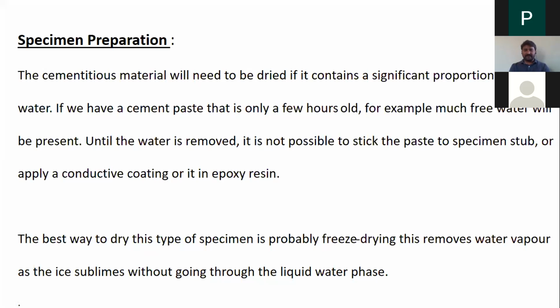Then we may use even diamond polishers to get a very fine surface, so that if the surface is very fine, the quality of images that we get will be very high. If the resolution is very high, then analysis can be very prompt. So sample preparation is very, very important. There are lots of papers available on sample preparation. Sample preparation itself can be a 1 hour topic. It is very, very complicated. But please note that before going for SEM analysis, sample preparation is very, very important.